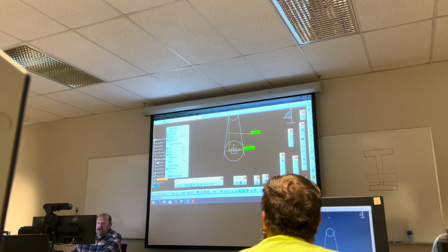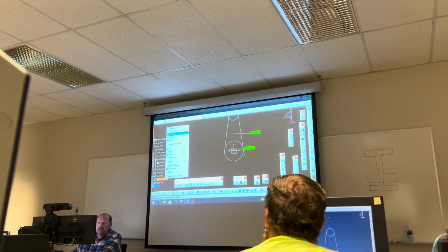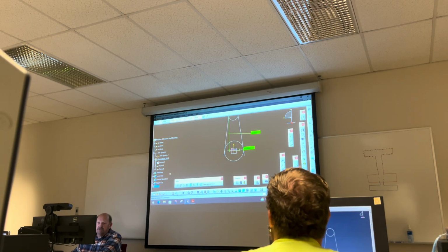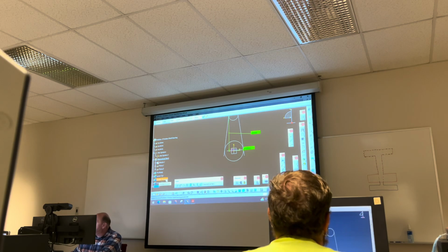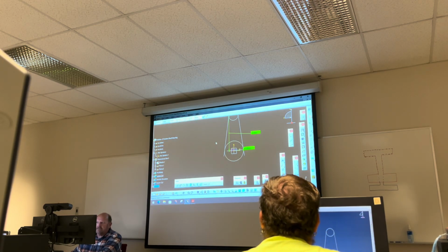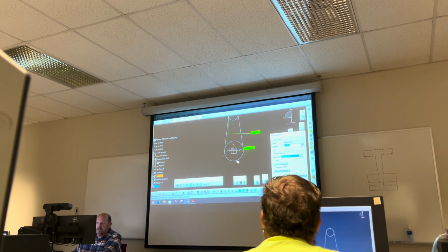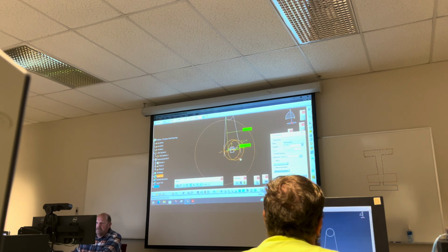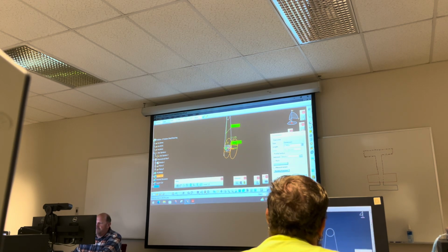And I'm going to define and work object this middle structure. Or before I do that, let me do this. The lower cylinder on this is 3 inches, so I'm going to say define and work object. And I'm going to make a pad out of this. And I'm going to reverse the direction on that. And this is going to be 3.